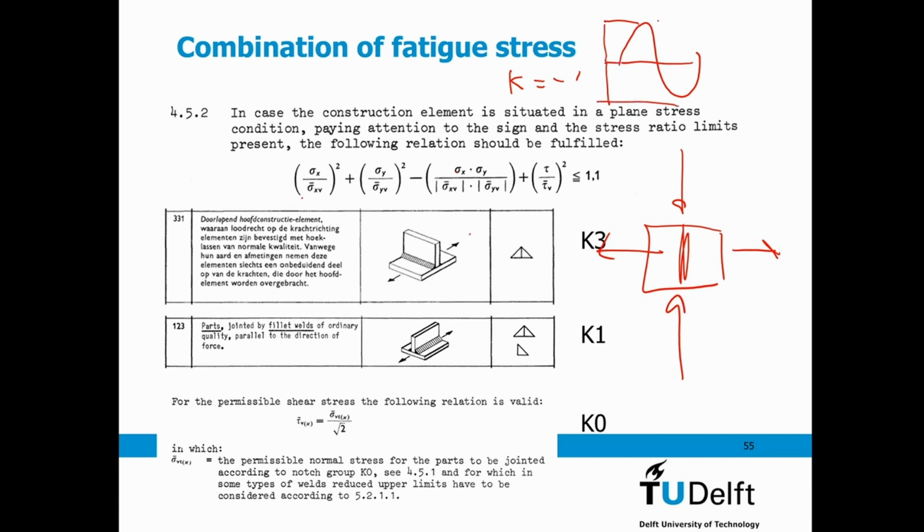If this one is, let's say, 20 and this one is -21, then this is compression, while if this one increases to 22, then it is tension again in this rule. So the sign might easily swap. Pay attention to that if you happen to have that situation.